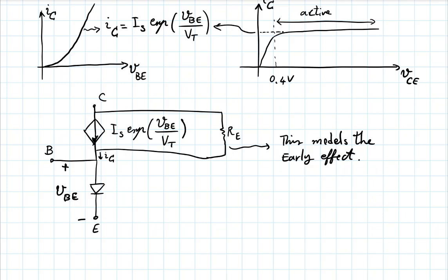And now you might say there is a little bit of a trouble with that. Is this a good model? Does this accurately represent a situation where I have that current plus a current that only depends on VCE? Does anyone see any problem with this? Well, there will be a current through the resistor, but that current, you're saying it doesn't depend on VCE.